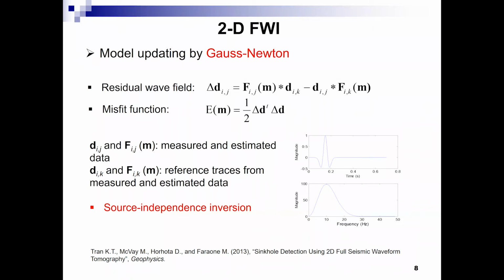So we can use any source signature for wave simulation to answer the question, right? We can use a Ricker wavelet, we can use a sine function, or even a triangle wavelet to simulate the waveform. And then we do the convolution like this. We don't need to know the actual force applied to the ground because we don't measure it using the sledgehammer.